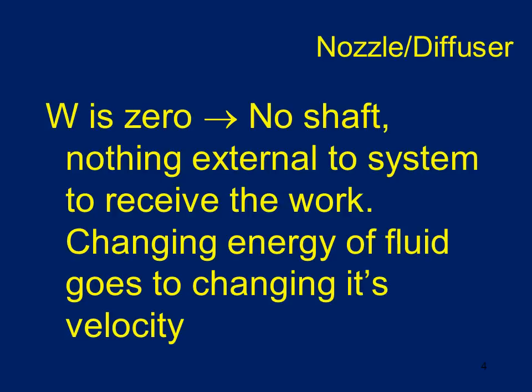Notice on these devices that the work is 0. There is no shaft, nothing external to the system. It's just a simple, let's say, cone or a truncated cone. Nothing external to the system to receive the work. The changing energy of the fluid goes to changing its velocity and not to producing work. So what you have is something that will speed up your velocity but will not produce work for you.